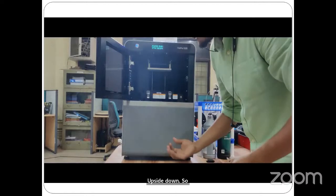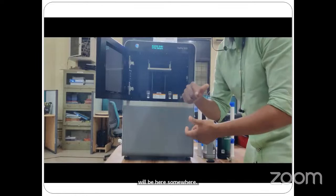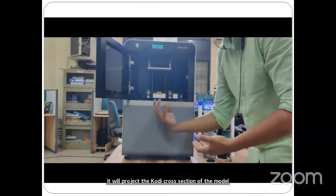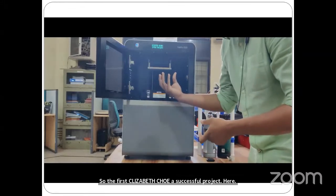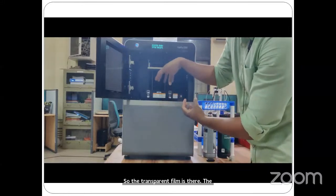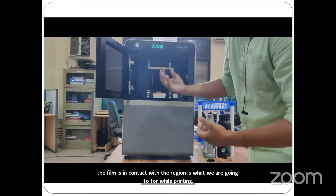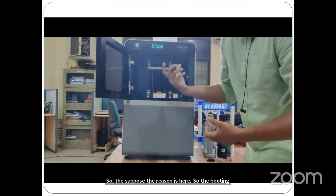Now this is the setup. The projector will be here somewhere. The projector will project the 2D cross section of the model that you want to print. It will have 2D cross sections throughout the height. The first 2D cross section, it will project here. You have seen the vat is transparent, so the transparent film is there. The projector light will project the 2D cross section onto that film, and the film is in contact with the resin that we are going to pour while printing. Suppose the resin is here. The 2D cross section will cure that much area with the projector light.